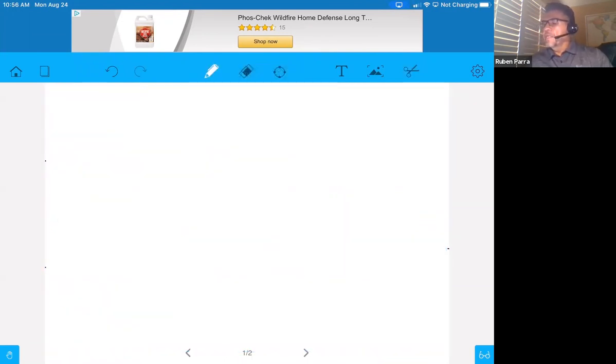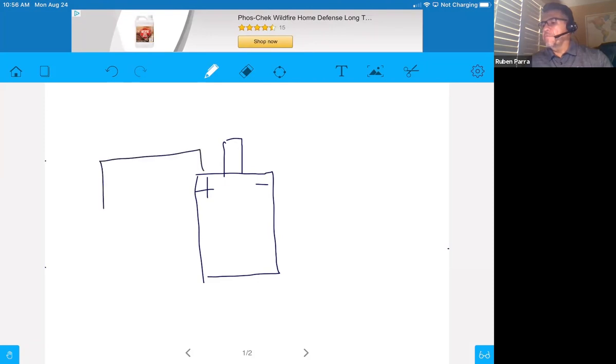Let's say we're looking at a coil, and I'm going to draw an old school bottle coil. All coils have a positive and a negative. I don't care if it's a one coil system, a two coil system, whatever it is. The proper voltage means you've got to have your 12 volts going to your positive side. Of course, the negative goes to a type of switch. Don't worry, we'll talk about that in ignition systems. But what they mean is 12 volts going to the proper side of the coil.